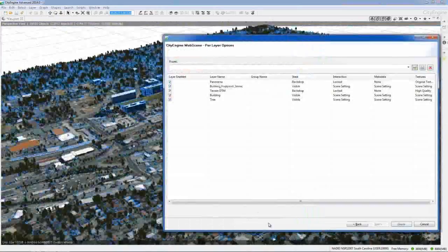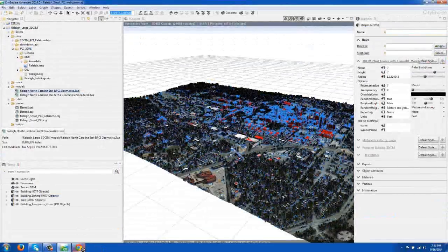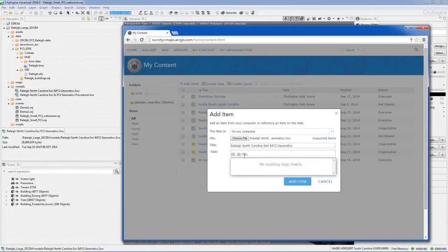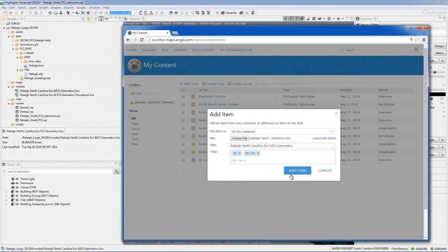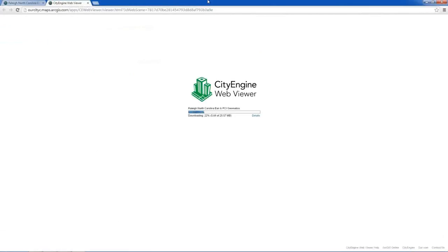And also we can then export these iconic models with the full scene that we created earlier directly onto ArcGIS Online. So first of all, I showed you how to export that. Now we're going to show you how to load it onto ArcGIS Online. You can do it out of CityEngine, or some people like to just use the online interface, and they can choose and drag the file, select some metadata tags, figure out the name, and then it'll load this data directly onto Esri's ArcGIS Online systems. So once you've got it loaded online, you can open it in the browser, you can add images, you can customize text, and it's going to load up this Webscene.